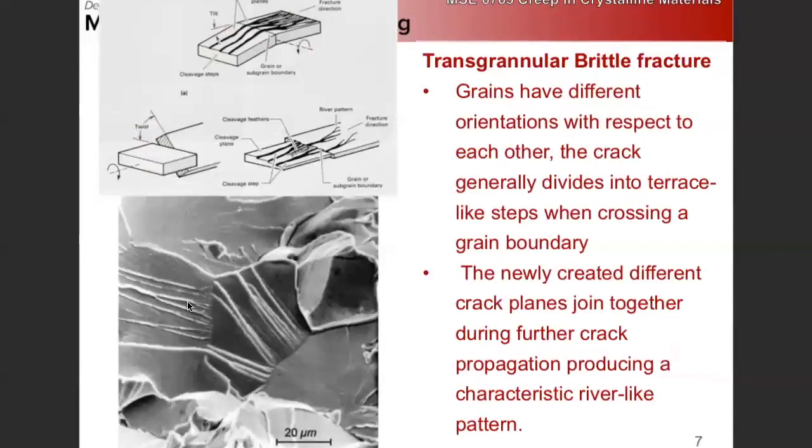Here, I was convinced I knew that the crack started this way and was propagating this way. And now that I look at it, I'm not so sure, because there isn't a propagation direction given. But people who look at these all the time can tell, right, by the orientation of the river marks, whether the fracture direction is going this way.